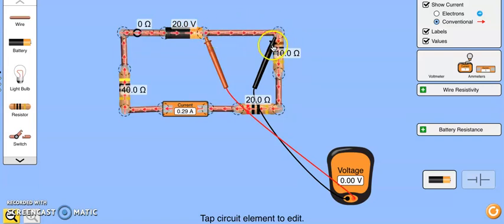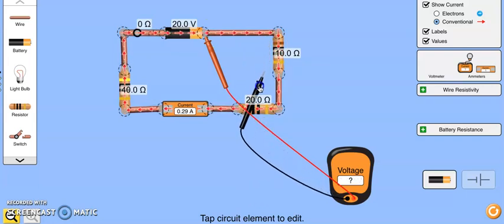And we learned in a previous lab, when current flows through a resistor, there's a drop in potential. So I want you to anticipate what will be the drop in potential, the difference between this spot and this spot when I put the black here. In the previous lab, it would have been 20 volts, but when we put it here, we see it's 2.86. In other words, it's a fraction of that 20.